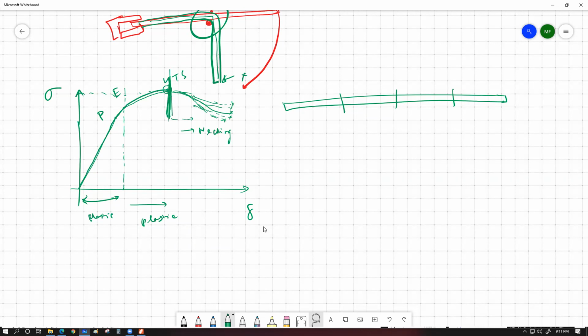But from this point beyond, you can have different lines of graph all the way up to the breaking. This cross line represents breaking, that the object has actually broken into 2 pieces, can no longer be loaded. It has been destroyed. Now, why could that happen? These were all manufactured in a single plant, in a single process, and you simply cut them off into 4 pieces, but they have different graphs. Why? Because of necking. Let me explain what necking is.